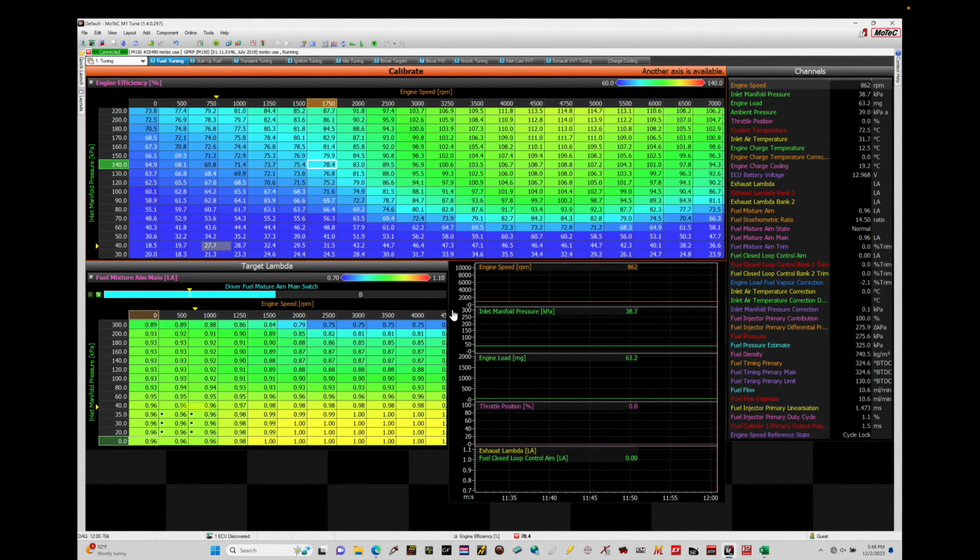Okay, so let's get started. We're going to be taking a look at setting up our pressure sensors in our Motec M1 systems. Now, configuring and setting up our pressure sensors is very straightforward. It's going to be a voltage to pressure scale lookup. We just need to tell the Motec what that calibration scale is going to be.